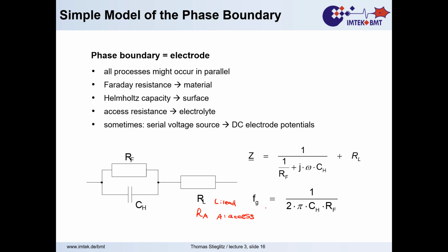So we get a cutoff frequency. That means the frequency where decay from the capacitive area is in transition to the constant area of the excess resistance, and exactly that transition gives us a hint where it is. That's the cutoff frequency here, Fg. G comes from German Grenzfrequenz, so you either find it with Fg or CO for cutoff, or it's mainly defined in the textbooks than in the text what the index means.